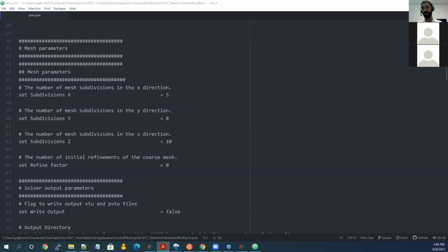You need to make sure that this number is not large, because if it's large, it actually engages other points which are not on the boundary and assumes they are on the boundary. So you need to be very careful about this. Usually I would select 0.01, or maybe smaller. So you need to be careful. You need to simulate and get this parameter optimized depending on the round-off error of your mesh generator tool.